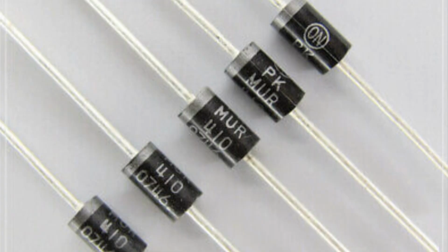But in the body of the diodes, when you're having your diodes, you need to read it very well. The names and the capacity of the diodes are always indicated on the body of it. It's written on that black side of it. So when you are trying to replace your diode in your circuit, you have to read through that, and you have to measure your diode before replacing it on your board.